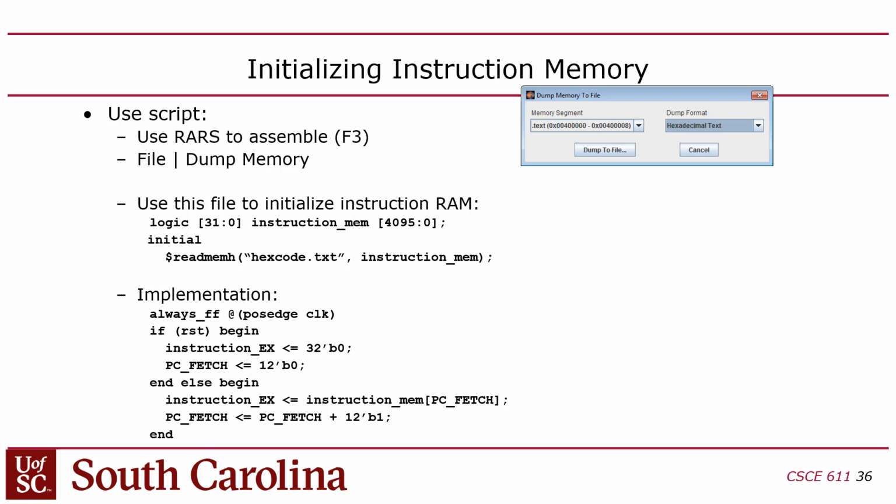So if you put the last 4 switches 1, 1, 1, 1, that's 15, right? But in lab 2, it wouldn't show 15, it would show F, right? But in this lab, we're going to have the CPU do the translation, so it'll actually say 1, 5 in base 10 instead of F, right?